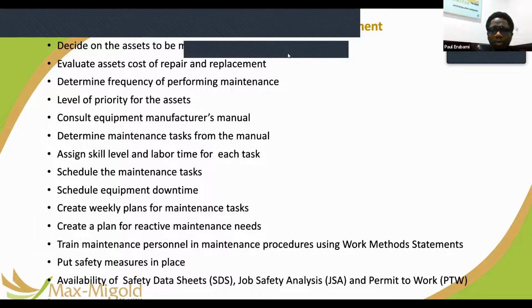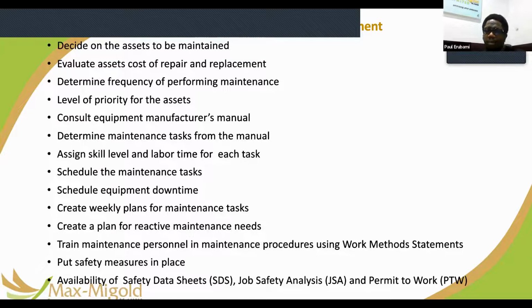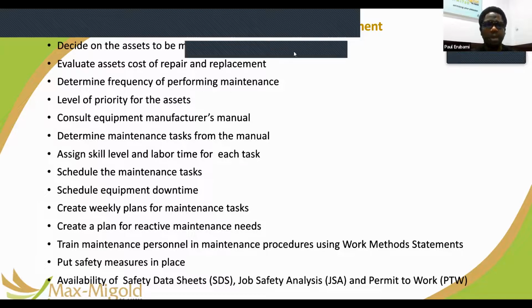You now know how to schedule the activities, because part of maintenance plan preparation is thinking of your maintenance as something that creates downtime on its own, right? And because it creates downtime on its own, you have to be careful when to put that downtime. So you don't go and shut an equipment down for maintenance at the time it is needed most, right? So you want to reduce the impact of your own maintenance of that asset on your organization, because that's what happens if you come to work like every other person and you decide to shut the gen down by 9:30 a.m. because that's when the contractor showed up to do the servicing, right?